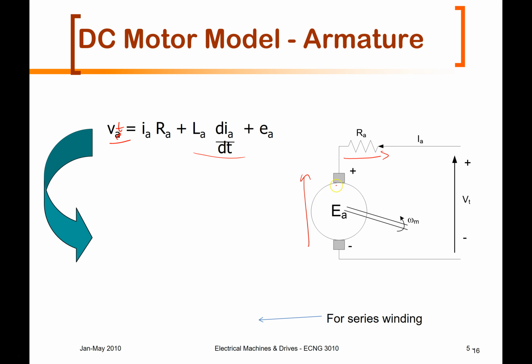So remember, inside the winding, we have coils of wire on the armature. So these windings, because there would be some inductance associated with it, every time you cross the commutation point, even though it's a DC machine, remember we had those little dips in current. So every time you have those dips in current, that is a di/dt, and that would mean you have some voltage drop due to the change in current.